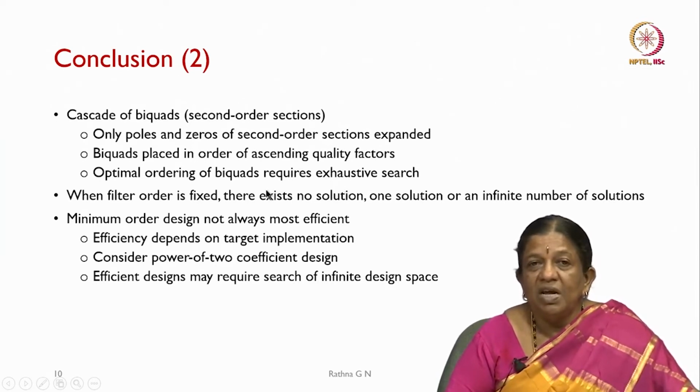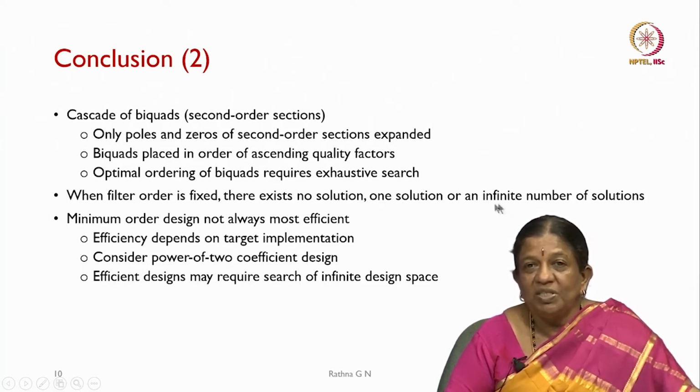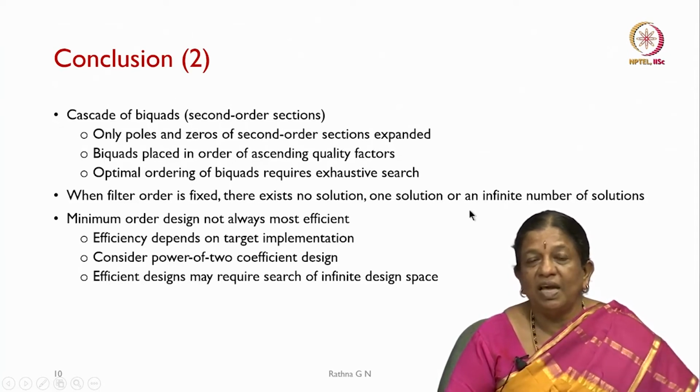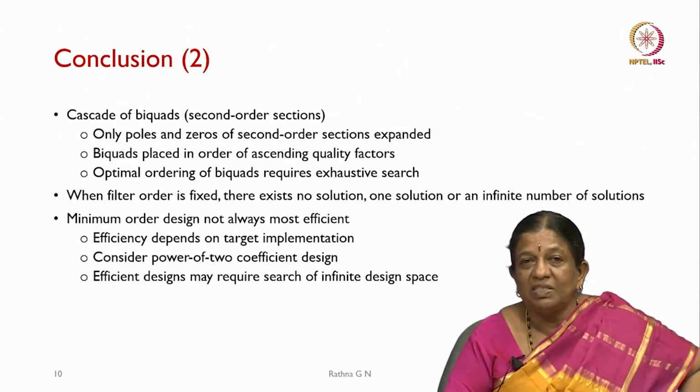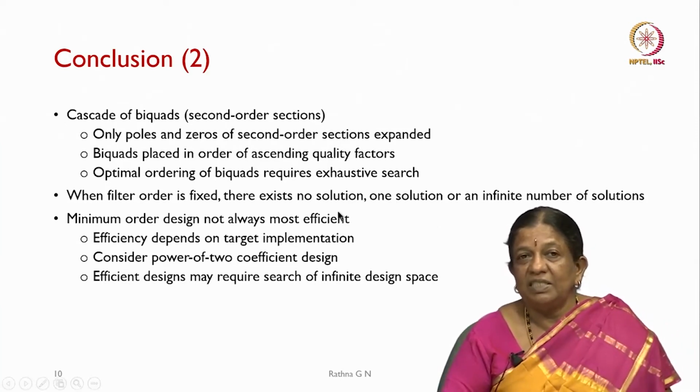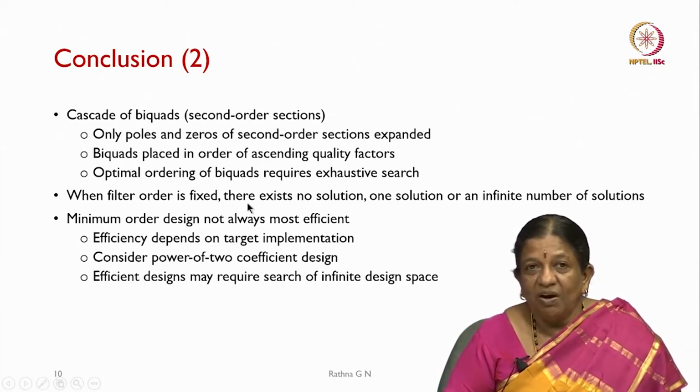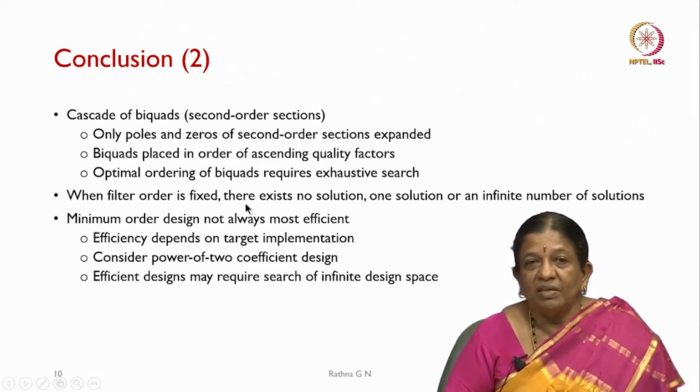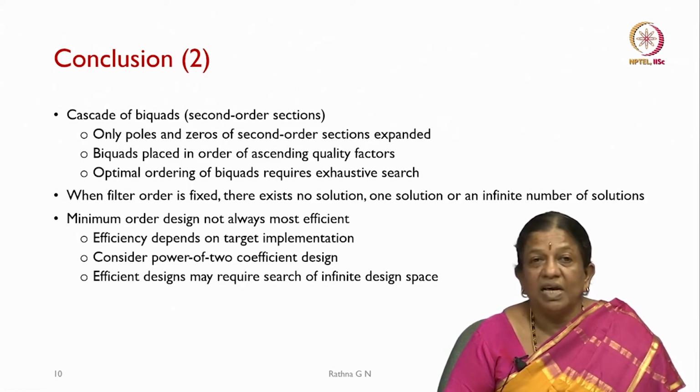But if the order is more than 2, for example equal to 4, I may have 2 options. This can be first, that can be later, but still I can alter my poles and zeros across the sections and achieve an optimal filter structure, and my instability is going to be much reduced.